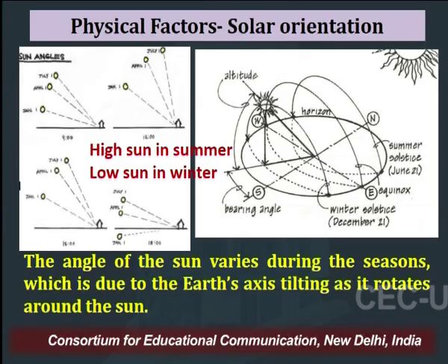In the summer the altitude of the sun is higher, and during winters the sun is at a lower altitude. Because of these two aspects, the fenestrations are decided in any design project. So, in our residential design project, we need to take this factor as an advantage and design accordingly, because during summers we do not want harsh sun to enter our room, our building, our home. But during winters we all love the sun and we want that sun to come inside the house.